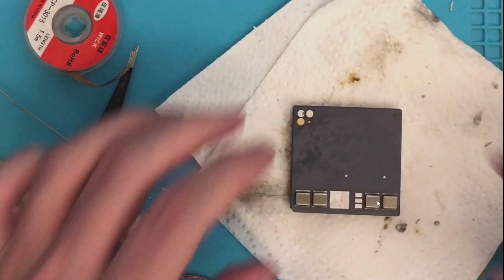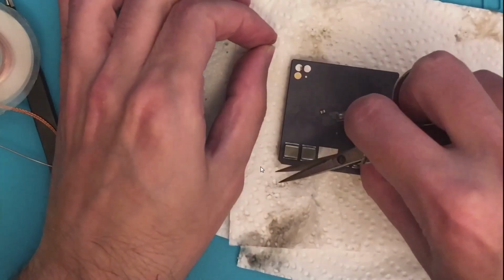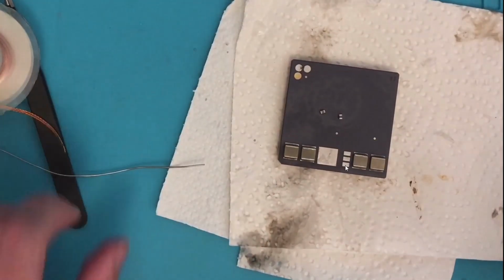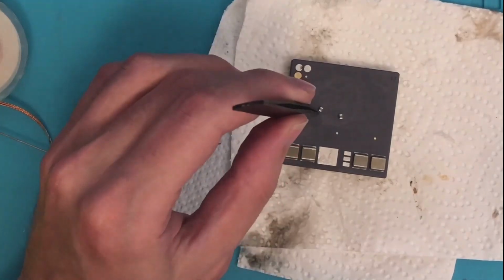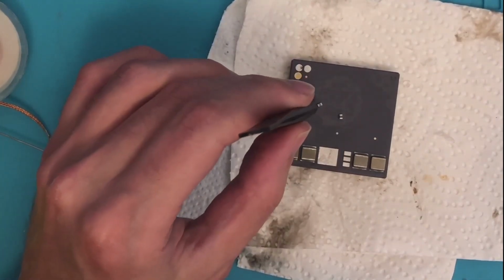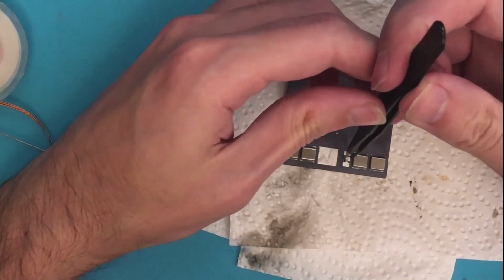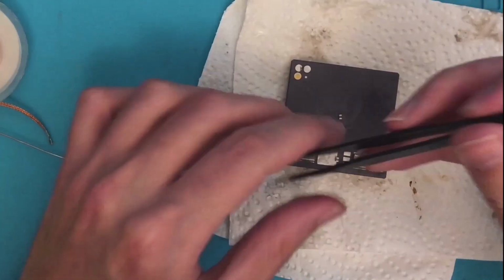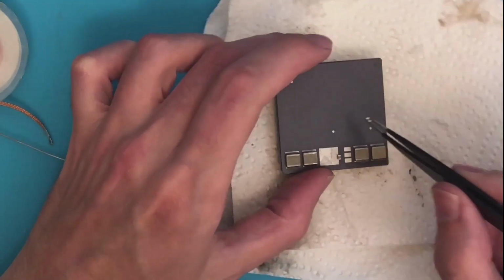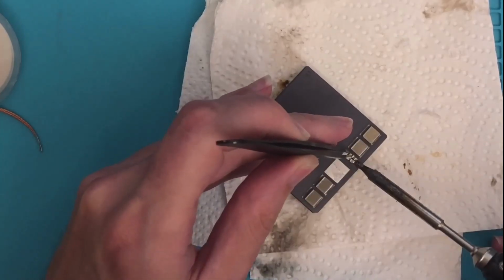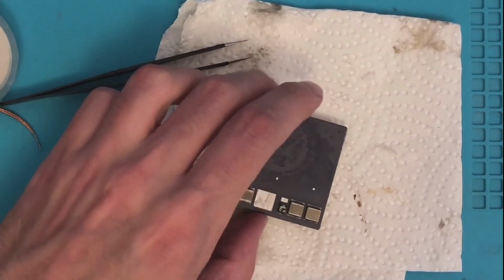So now here is our very clean CPU. The first and the last two capacitors are connected to the output. These are actually only 3 microfarad each. And now that the power comes with a wire, maybe it's a good idea to add a little bit more here. So these two, each one is 100 microfarads and can be nicely placed here on these two bottom pads, as one is ground and the other is the output. So I soldered this, and this is the result.